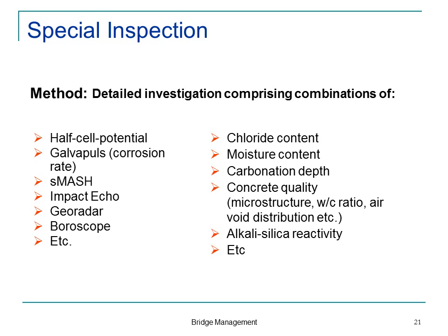And some of the things we look for, well, of course, we always look for moisture content. If there's a part of the structure that has a higher moisture content than the rest, then we probably have a problem there. We look at the chloride content. Chloride was the part of the salt that gives us corrosion, and if we look at a profile of that, then we can get a rough guess about how fast it penetrates. Yep. We could take samples from the concrete.